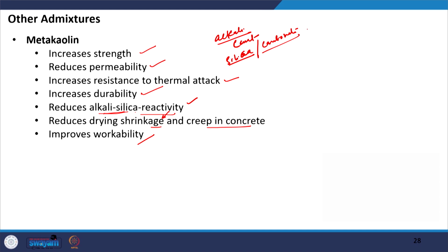So, we can have silica and carbonate from some specific aggregate type. Okay. So, usually the aggregates are more inert in nature, but some of the aggregates can have active minerals. So, it is important that in order for these reactions to happen, you should have active minerals present in the aggregate.